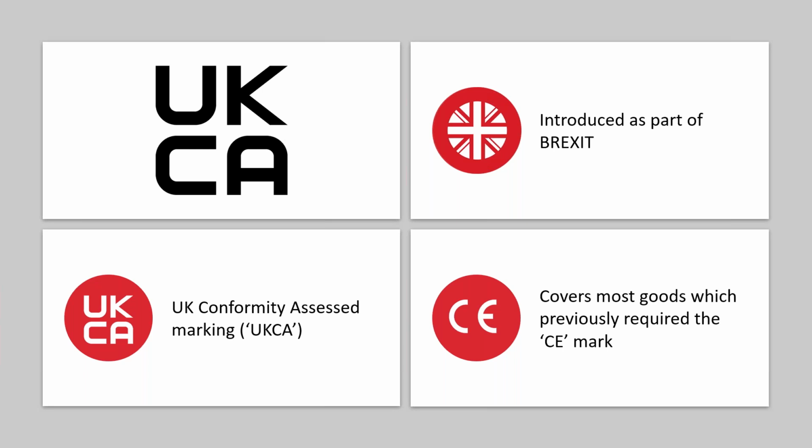Now, in the case of hazardous area equipment being installed in the UK, the ATEX directive was going to be replaced by the UKCA and the UK directive SI 2016/1107. So this was going to be known as the UKEX scheme. So in addition to the notified body and QAN issued under the ATEX directive and the QAR issued under the IECEx scheme, a separate UK-based approved body and UK QAN must be applied to products under the UKEX scheme.